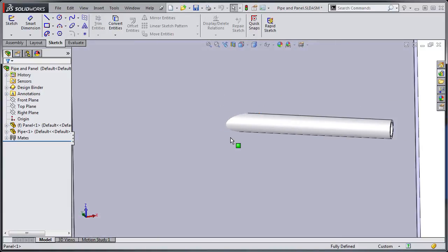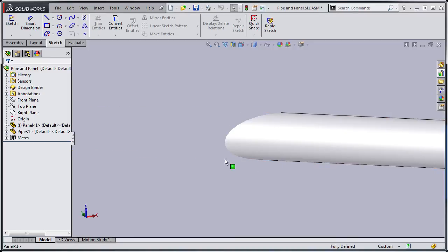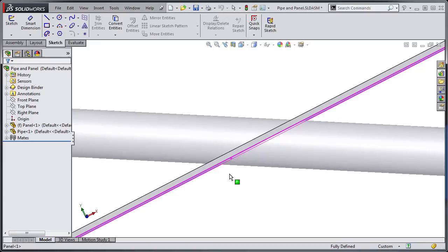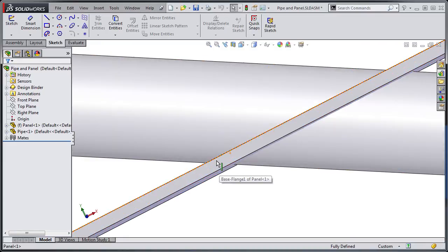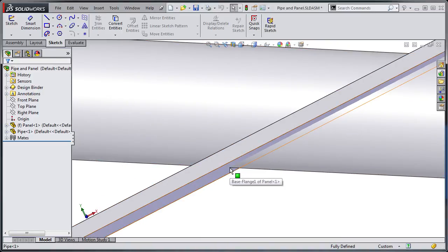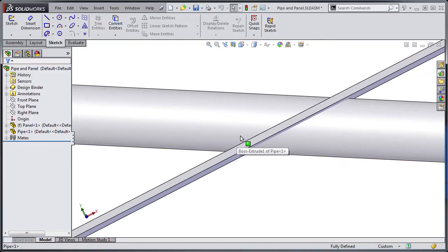So how do I go about doing that? Well, firstly, I could try and use that sketch that I just created, but the problem is that when I go to cut through, if my material is too thick, then either I end up with an angled cut, or I end up with too much land on one side, which would cause an interference. Doing a normal cut would allow me to go through like that, but it would interfere with the pipe.